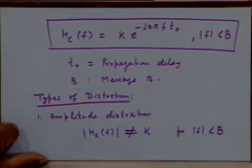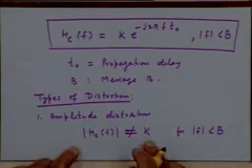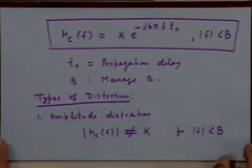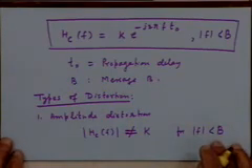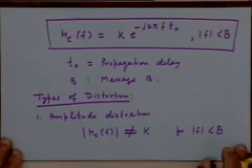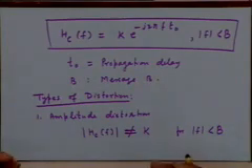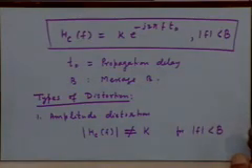Okay, if the magnitude characteristic of the channel is not constant, equal to some value k which denotes the attenuation, then we say that over the bandwidth of interest the channel is introducing amplitude distortion, in the sense that the different frequency components present in the message waveform m(t) are being amplified or attenuated differently by the channel.